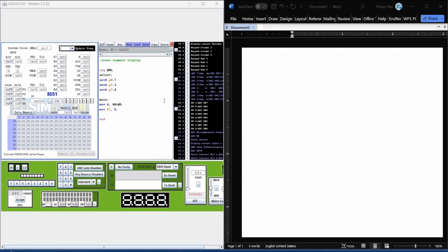To do that, if you want a particular port, either A1 or A0, to come up, or if you want to select it, you use the instruction set B on that particular port or pin. If you don't want that pin to show, or if you want it to be zero, since we are using ones and zeros to demonstrate, you use the clear instruction, CLR. So let's run this code, then we'll see where our LED would display.